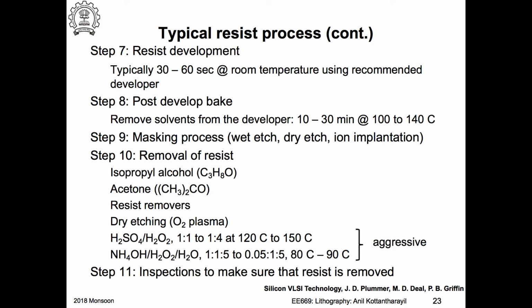So what would be the consequence of it? If it is specular reflection, what happens? The same light is going through the photoresist twice, so it is more likely to be absorbed. So the apparent dose will increase with specular reflection. But what about diffused, non-specular reflection? This part is not supposed to get any light in the first place.